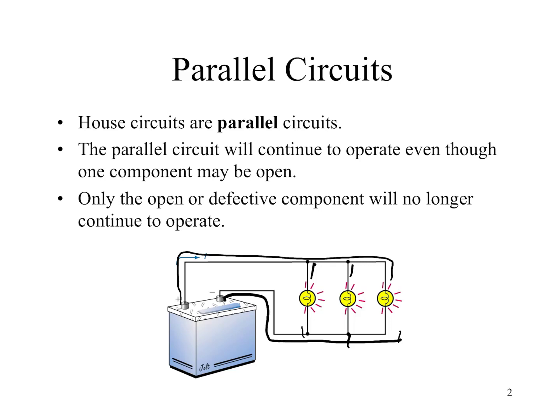So that being said, for a parallel circuit, because every load is connected to the source, or connected to the voltage, we can say that for a parallel circuit, VL1 equals VL2 equals VL3, where each one of these lamps is L1, L2, and L3. And so in a series circuit, we had current as the common quantity. In parallel, we have voltage as the common quantity.